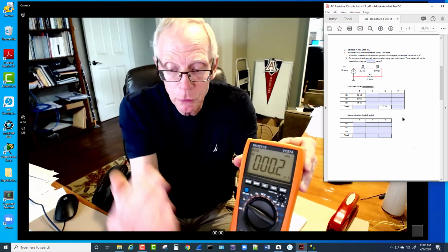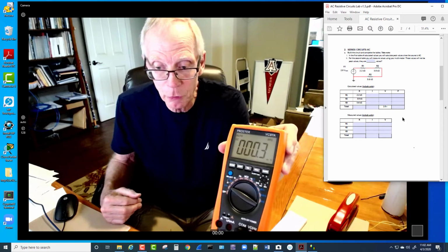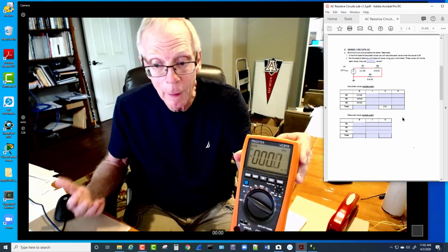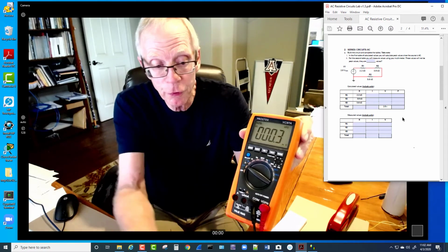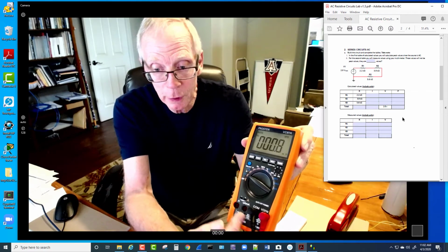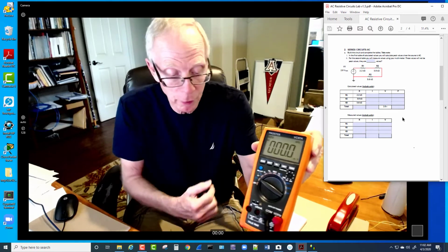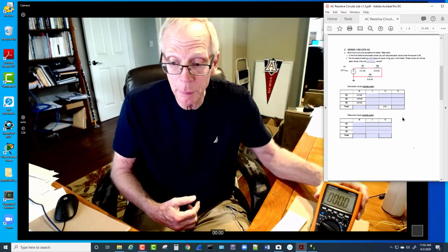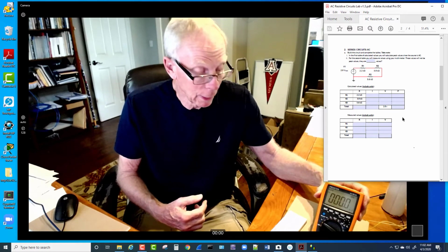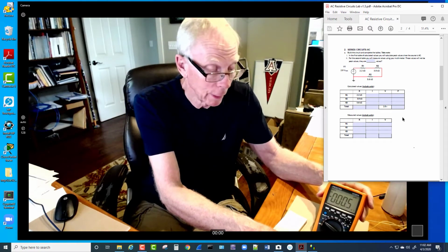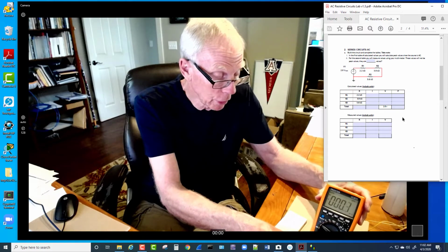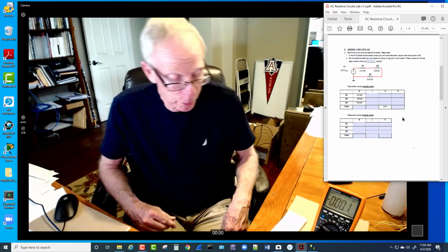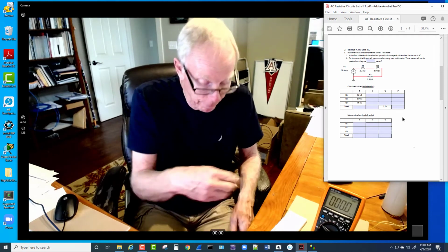For the currents, you do have to select the range, whether it's amps, milliamps, or microamps, and that's because things are fused, and you're still stuck moving the red probe over here for those. Okay, so we've got that as a meter and a couple of basic things. We can use it right away to measure a couple of the resistors before I apply a power supply.